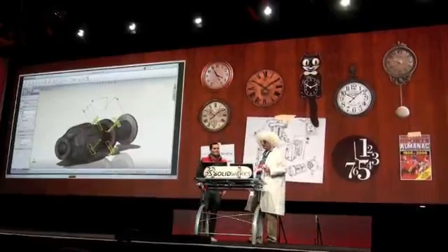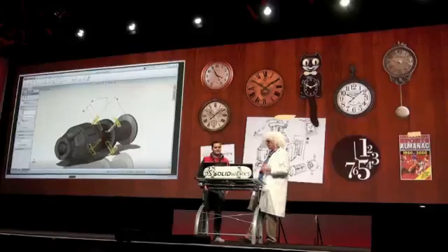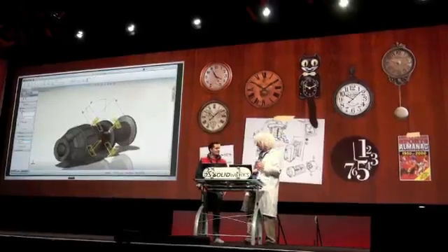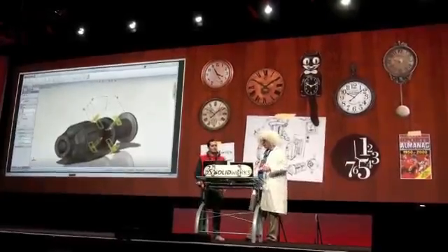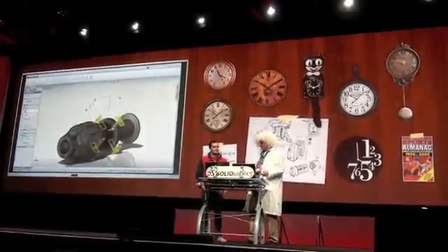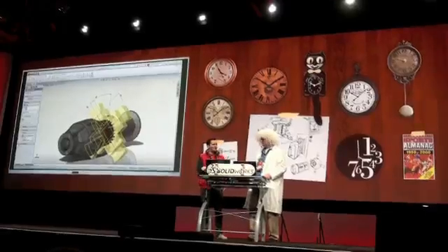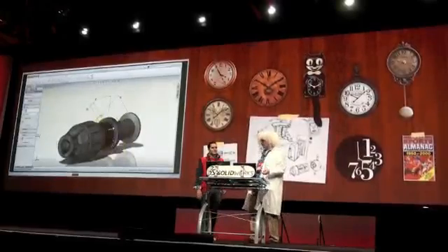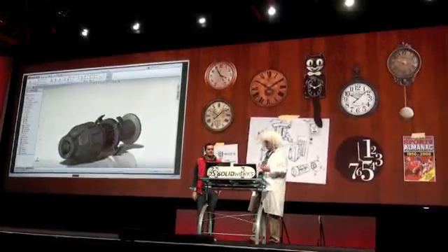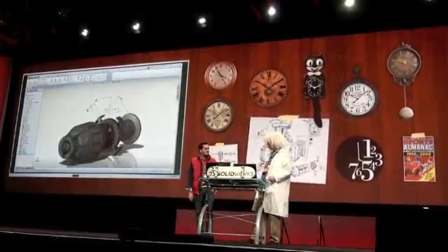But you know what? Something else in 2013 they added was the ability to directly enter equations in any property manager. So, for example, I can tie the web thickness to the height of the vane. But what does this mean for the design? Well, as I adjust the vane height, the thickness is going to update automatically. It really does give you incredible flexibility.